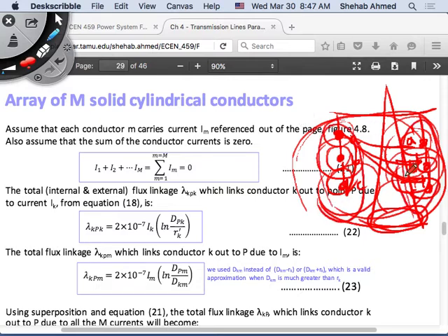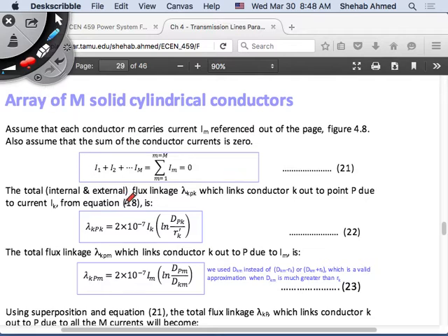This is another three-phase circuit. So IA plus IB plus IC plus IA prime plus IB prime plus IC prime is equal to what? Also 0, right? So this identity will always hold. The sum of the currents in a plane will always hold, because we're either going to carry a double circuit or a single circuit. Regardless, this identity will always hold here. So this is something we will use to simplify.